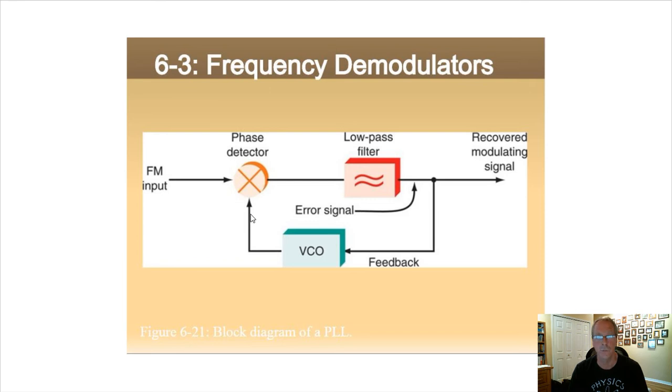Okay, so it's a control loop. If they're not 90 degrees out, let's say they're 80 degrees, it's going to be a lower voltage. So it's going to change the frequency here of the VCO to force it until there's a 90 degrees relationship. Once there is, the phase lock loop is what we call locked. Okay, that's a locked phase lock loop. And once it's locked, any variation on the FM input will steer the VCO frequency output to keep these two signals 90 degrees.